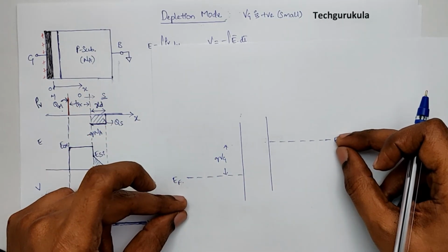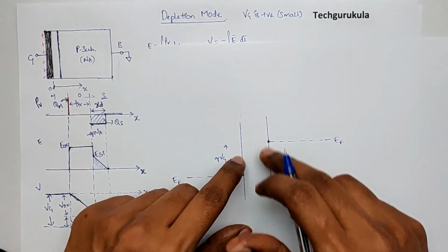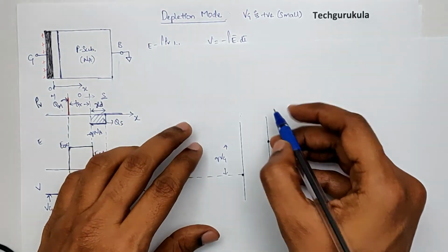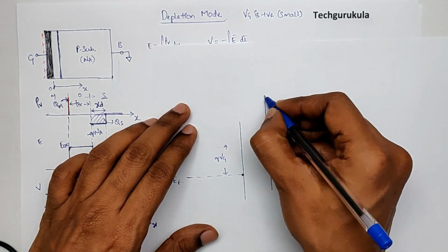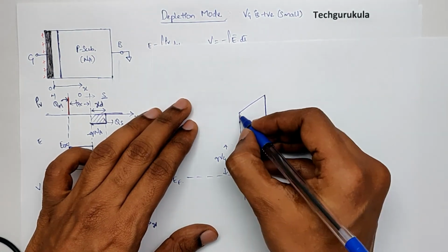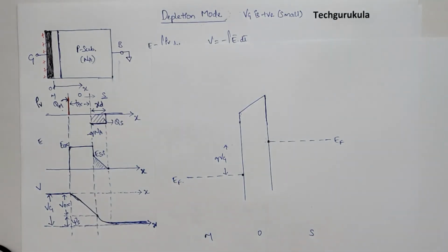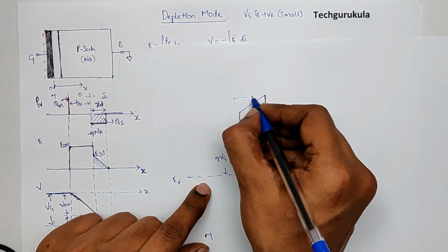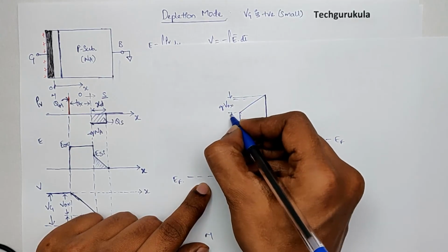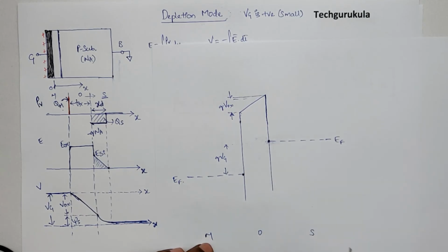Hence, we have this, which means if these two points are like anchor points for the oxide energy band gap, the top edge should also have tilted. So I'm going to draw that tilted. It is tilted. This is EC of the oxide. This is the metal, the oxide, and this is the semiconductor. This will be the potential drop across the oxide. This is Q times Vox. Now it's all about drawing how the energy band diagram looks in the semiconductor.